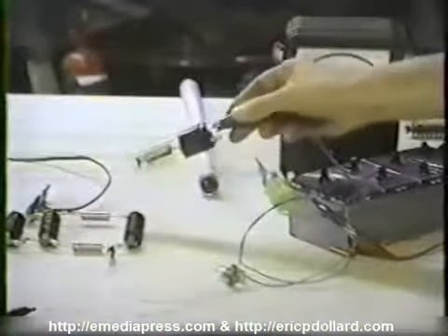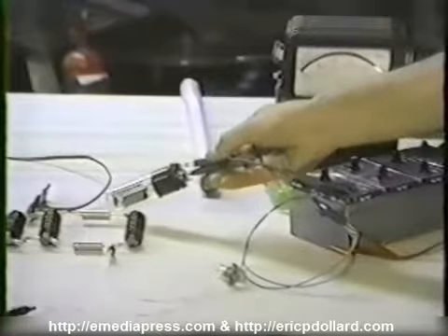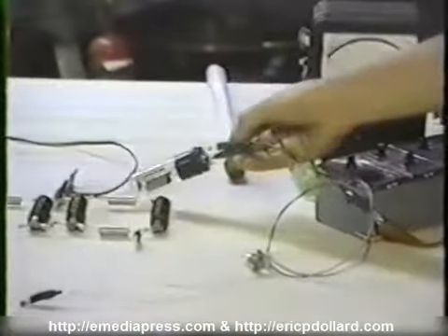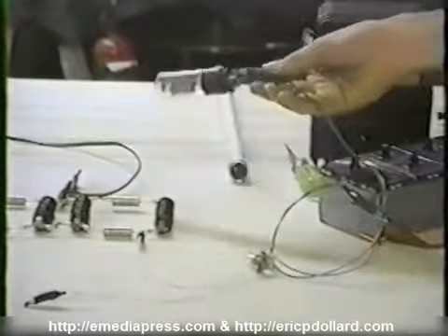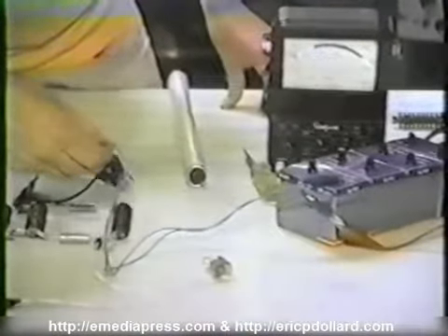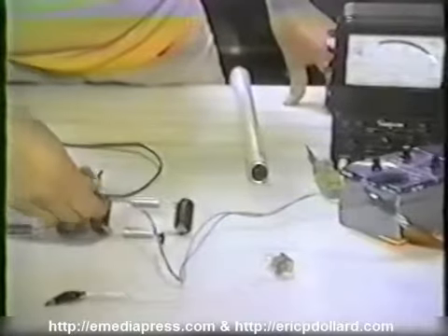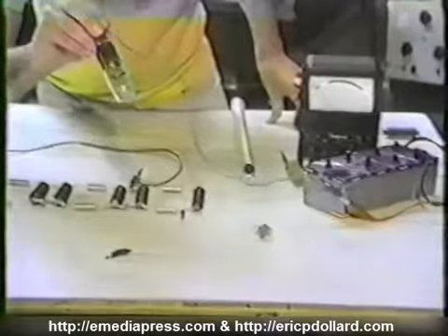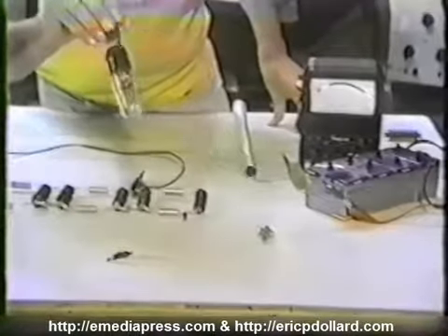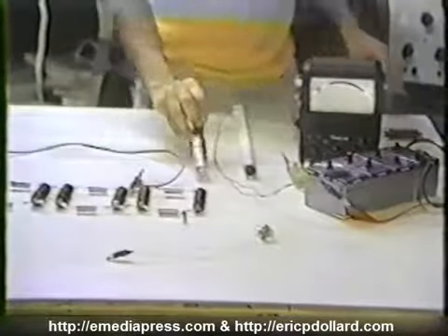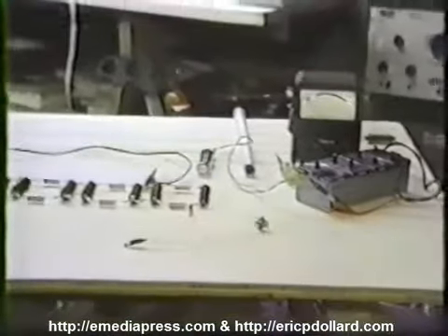And we can see that the phototube responds quite readily to the longitudinal dielectric induction existing at the end of this, primarily due to the presence of ionized gas. Get behind here so you can see the meter. See, it just jumps right up. Even though the illumination by the gas in there is barely visible, and of course I have a big 750 watt bulb hanging right up there in the ceiling, and that produces hardly any output at all. Now we'll go back to the board and do a little brief description of what multipactor action is all about.